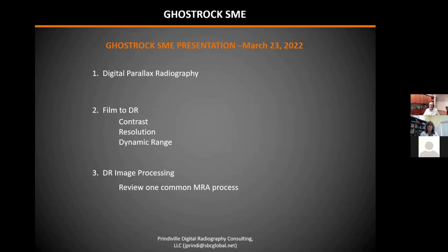So it does allow you to take advantage of the increased contrast to noise that digital offers and allows you to say, if I can see a smaller hole than I'm supposed to be able to see, then I can reduce my resolution requirement this far. They call that the compensation principle. You're compensating for the lack of resolution. You're compensating for the fact that the contrast to noise is so much better. So that is in the specifications, and it does allow you to do that. Very good.